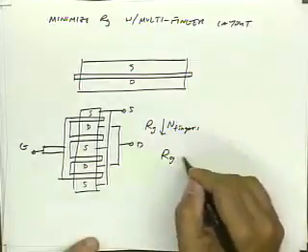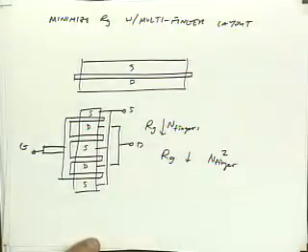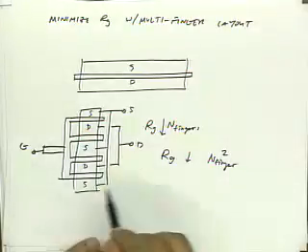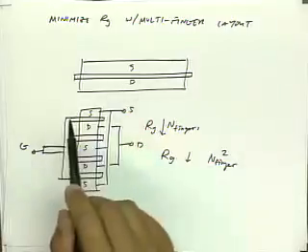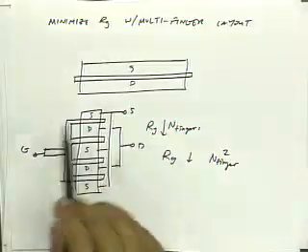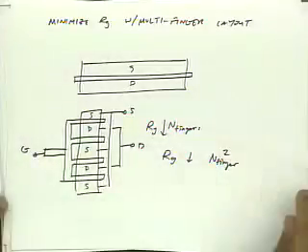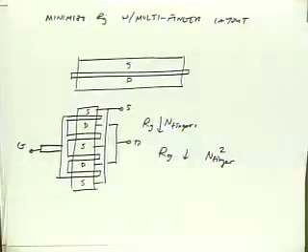So our gate resistance goes down like n fingers squared. So this layout is much superior to this layout. So the first thing you do when you do high frequency layout is you go in and make all your transistors multi-finger devices to make them nice and low gate resistance. Okay. Questions?